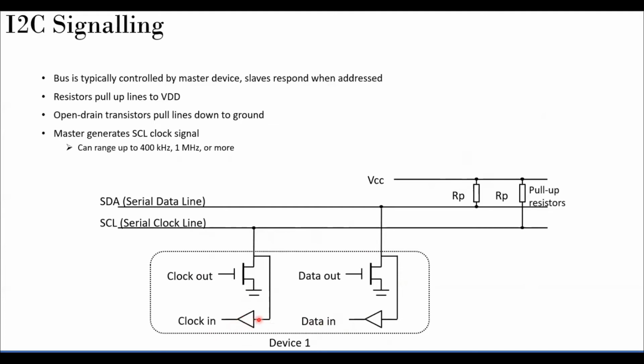Okay, so let's say you're putting a 0 here, then the pull-up is already done, so it will be going to the ground, and otherwise it will be in the high state. So no other things are possible for the buffer. For the clock, there are many possibilities, like we control the baud rate in UART and in SPI. Similarly here also you can control the clock frequency. Clock division is possible.